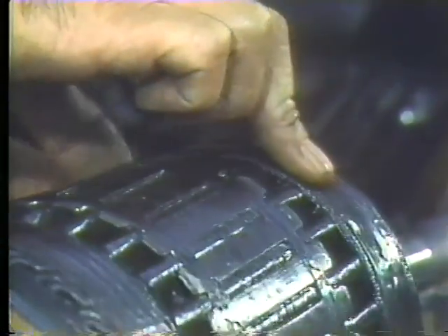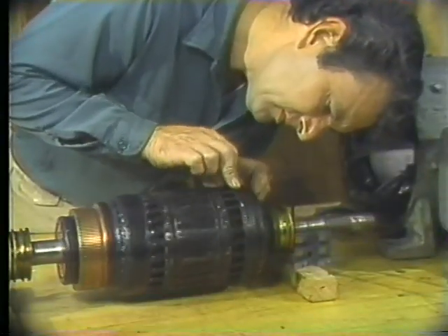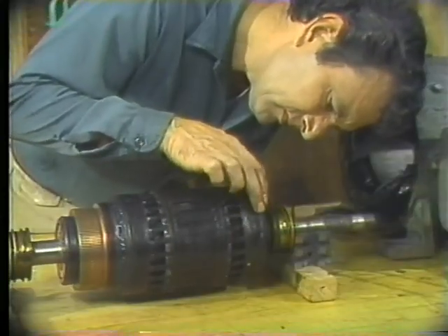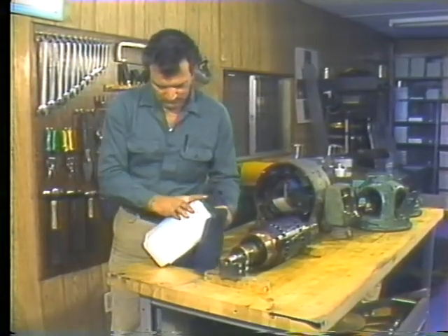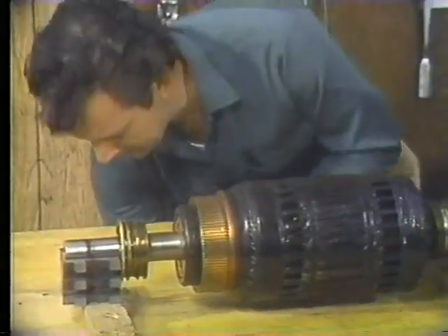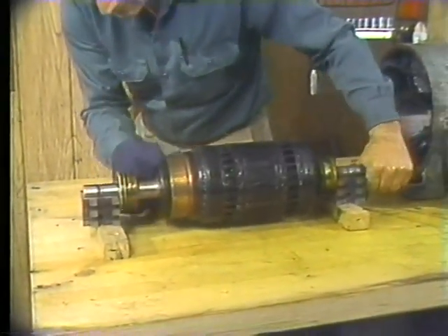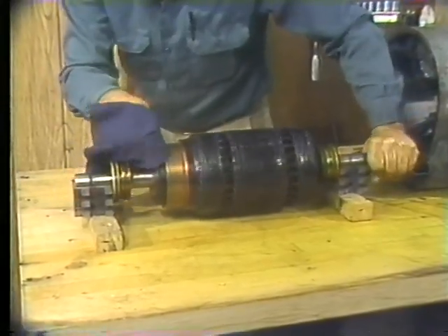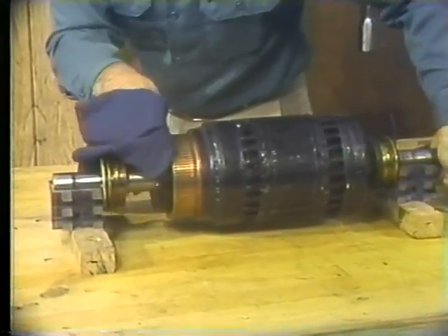Check the armature banding to be sure it's tight and intact. Check the back of the coils for damage. Pay particular attention to the condition of the insulation. Okay, the next step is to thoroughly clean the entire assembly. Make certain you're using an approved solvent and following all the safety precautions required. Be sure to clean the area at the front of the commutator, behind the risers, and the back of the coil windings. After you've completed your inspection, thoroughly clean the armature and repair any damage you found.